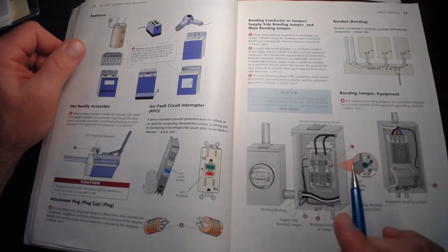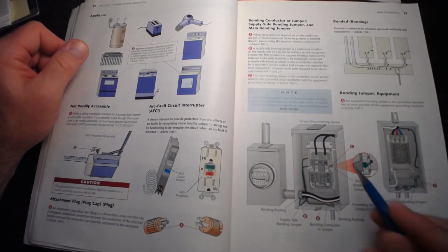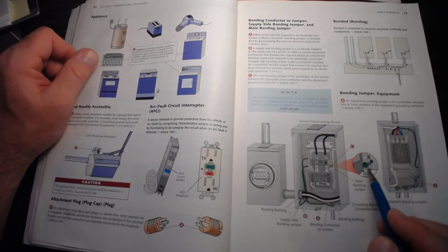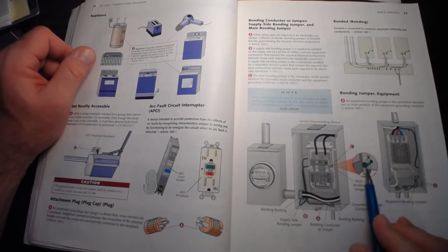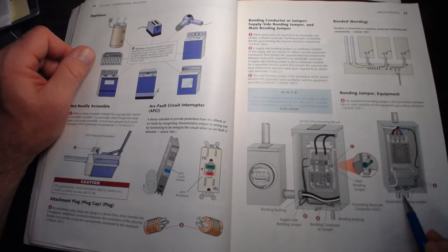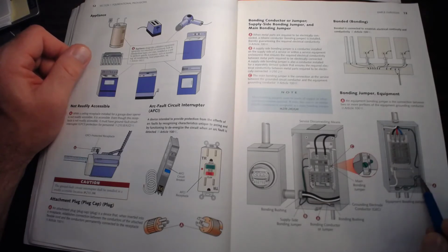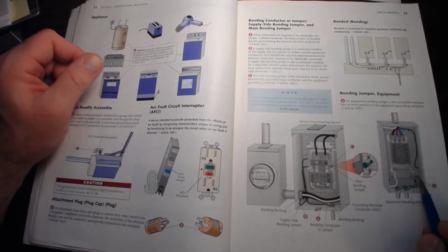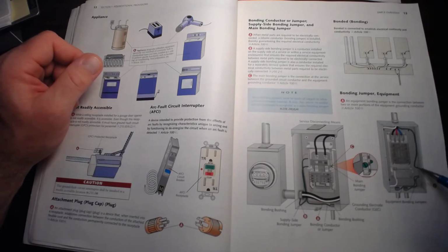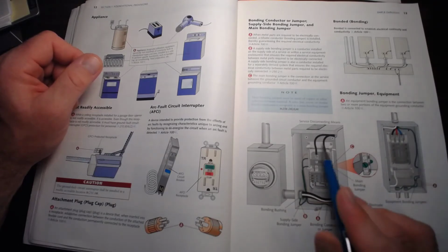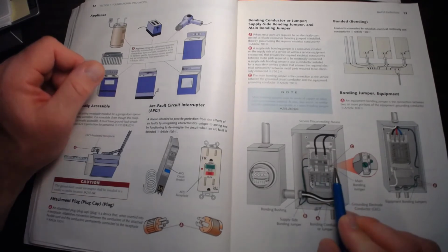Now at a sub panel, it's different because in a sub panel, you're going to have a separate neutral bar and a separate ground bar. You would not put a main bonding jumper in at that point. The equipment bonding jumpers are going to be connected from the equipment to the conduit, out to the equipment, over to the grounding bus. And we can see in this drawing, there's a separate grounding bus right here and a separate neutral bus, and these two are not tied together. So there's a difference here. You do not bond this in a sub panel, which this would be, and then you have your service where you do bond the neutral and the ground together.